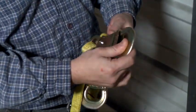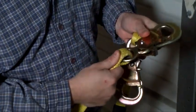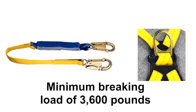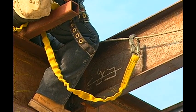A connector is a device which is used to connect parts of the PFAS and positioning devices together. These include D-rings and snap hooks and must have a minimum breaking point of 5,000 pounds. Connectors must be proof tested to a minimum breaking load of 3,600 pounds without cracking, breaking, or suffering permanent deformation. Snap hooks must be locking type.